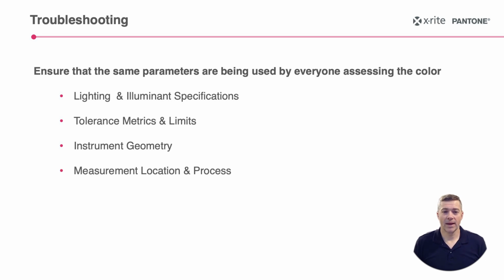Next, for non-opaque substrates, like certain papers or films, allow the backing material to show through. For example, if you measure on an ISO-compliant white backer and someone else measures on a sheet of white paper, you'll get different numbers. Ensure measurements are taken under the same conditions on the same type of material. Finally, consider whether the tolerances are realistic for the type of printing being done. Some processes are more variable than others, so you may need to adjust your tolerances accordingly.